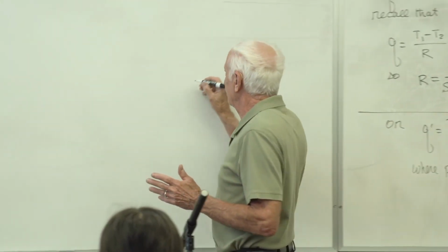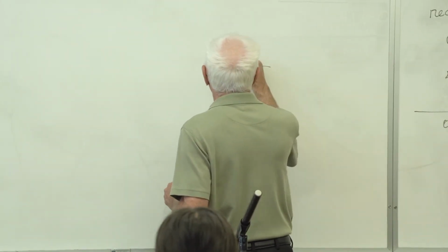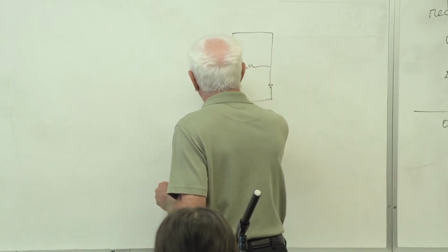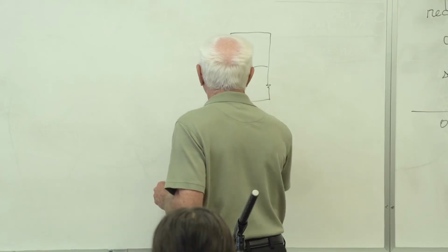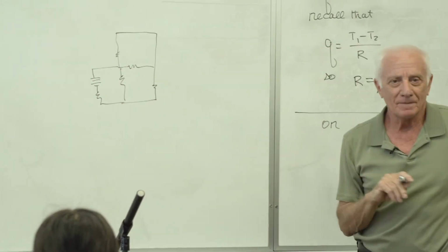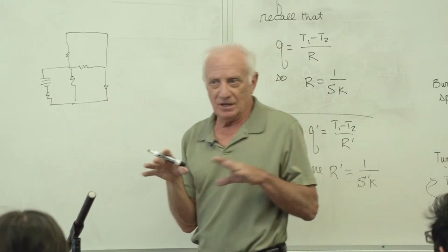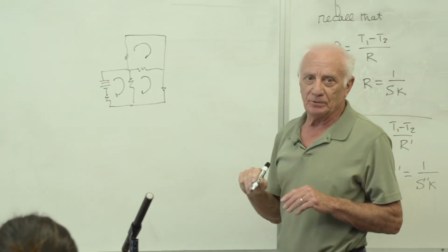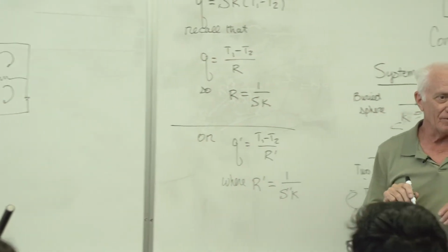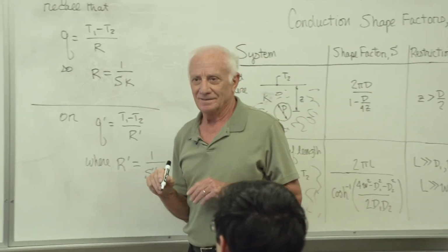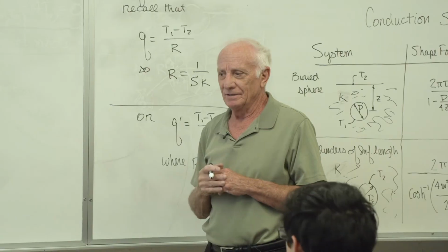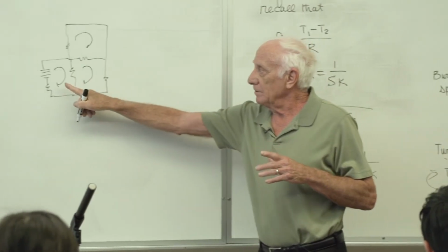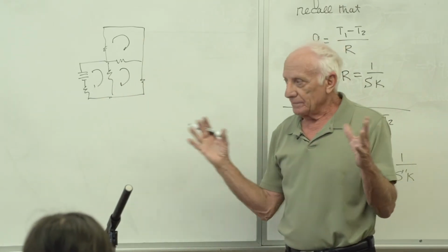If you don't know in that problem which way the currents are, I'll tell you what most people do. Most people, when they write the equations, they say I1, I2, I3. But notice what most people do. They assume they're all clockwise. Are they? Of course they're not. Then why assume they're all clockwise? Because I don't know which way they go. I'll take the easy way out, and I'll find out that this one might be the wrong way. He's going that way, or whatever. The math takes care of itself.